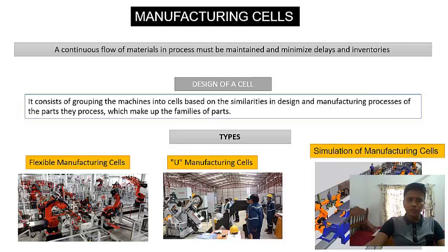U manufacturing cells. It is an arrangement of people, machines, materials, and methods with the steps of the process placed next to each other, through which the parts are processed in a continuous flow in sequential order, normally in the form of a U, that allows the flow of a single piece and the allocation of personnel flexibly through the concept of multi-skills.